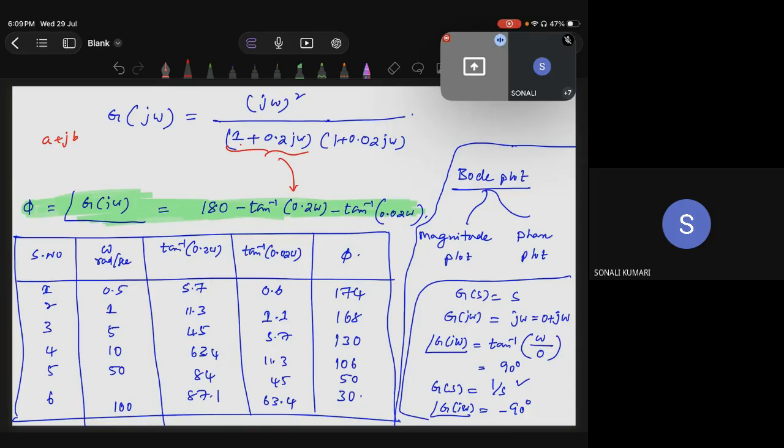If you don't understand, please ask me. So this table is clear. These are the omegas you have from before: omega L, omega C1, omega C2, omega H. Then you are choosing two other values, this one as well as this. For each omega, you calculate the first term and second term, and subtract those two from 180 to get phi. This is how we prepared this table.